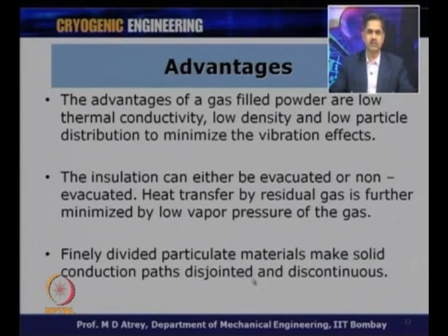So, we have some solid conduction which is disjointed, plus we have gas conduction depending on the kind of gas we are using, and the conductivity of the gas is pretty low. Therefore, while in the foam case we had a continuous solid conduction path, in this case we have a discontinuous solid conduction path, and therefore the Ka value in this case is less as compared to expanded foam.